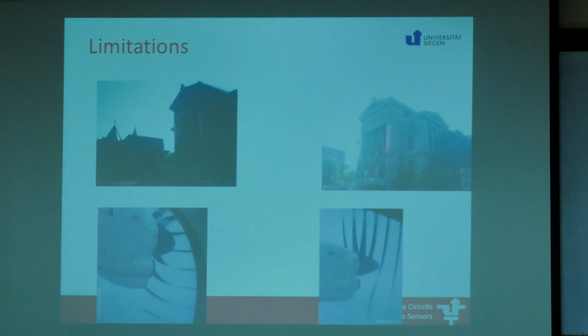Our human eye does a global shutter. It shuts, takes a picture. The old mechanical, reel-based cameras were also like that. You had a shutter, you take a picture. Our shutter is now each pixel gets reset one at a time. We read a row, we reset the row. We read the row, we reset the row. We read the row, reset the row. So we are doing a rolling shutter problem. Okay?